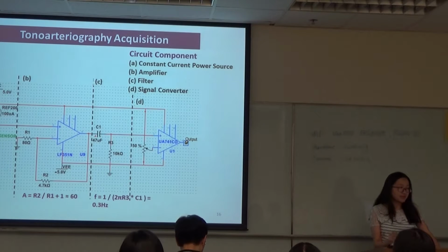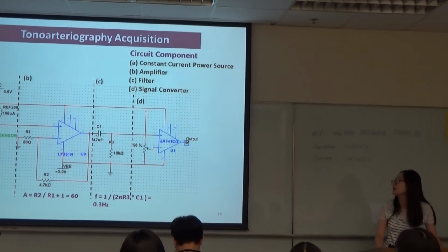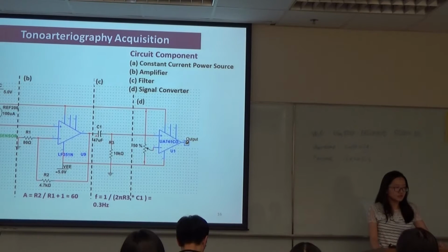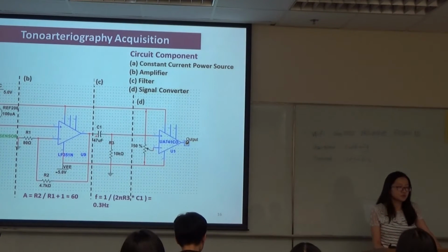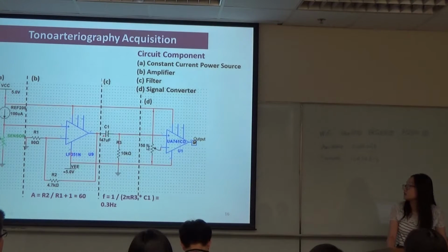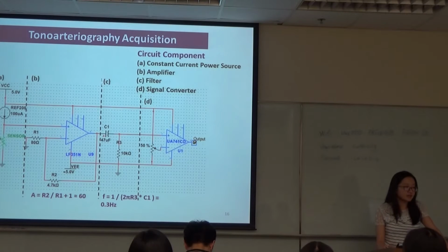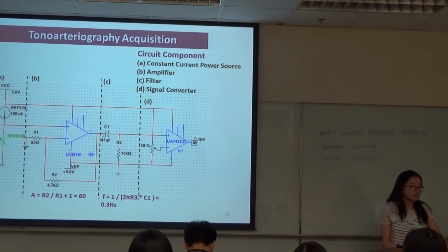We would like the peaks of the waves to be transformed into pulses, and then we will do an analog to digital conversion to make the detected signal waves digital. We choose the voltage comparator to achieve this goal. In electronics, a voltage comparator takes two analog voltage inputs, and then outputs one digital output to indicate which value is larger.